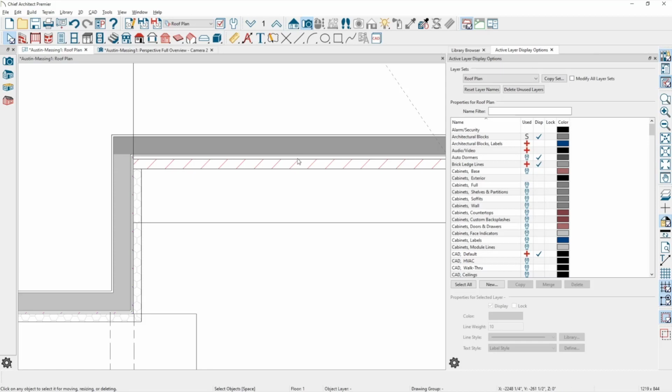So you want to see the outer and the inner. Okay, so I want to see 2 lines for the stud wall and 1 line for the outer brick wall. Or I don't even mind if I see the 2 lines for the brick wall, but I don't want to see the stud and the finishes and the fills.